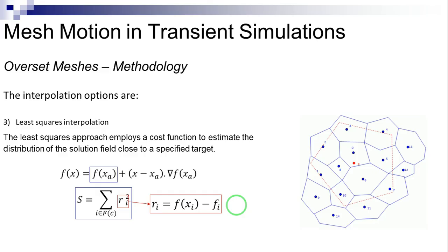In this illustration, face 0 is positioned nearest to face A. Only the neighbors of face 0, which are defined as any face that shares at least one vertex with face 0, are involved in the interpolation. The drawback is that some of the blue faces that project onto the target face, such as 1, 10, 11, and 7, do not play a role in this process.